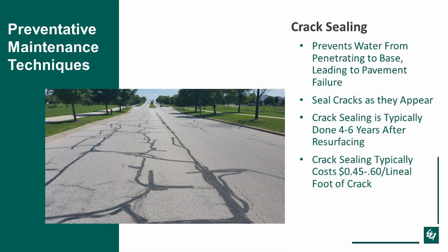Crack sealing, everybody's I think familiar with this one. It's utilized pretty much everywhere. It prevents water from penetrating the base. You're going to want to seal the cracks as you see them. A lot of municipalities will have a crack sealing program to go out and crack seal after the winter, find cracks, seal them right away. It can't hurt. You're going to prevent that water from getting to the base, and that's what you want. You want to try to stop that as soon as possible.